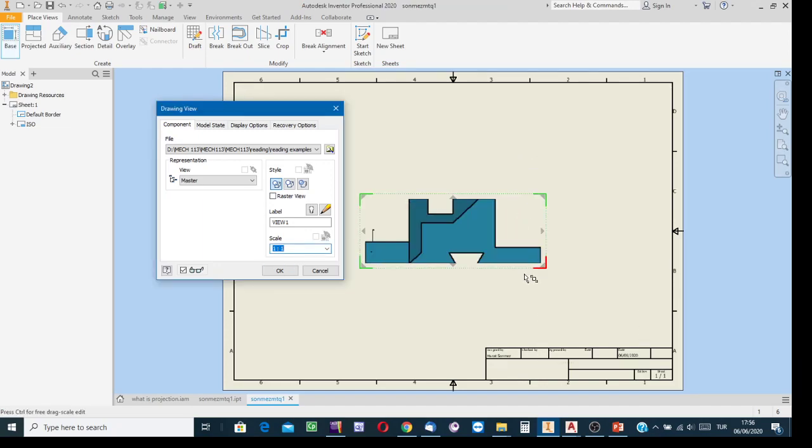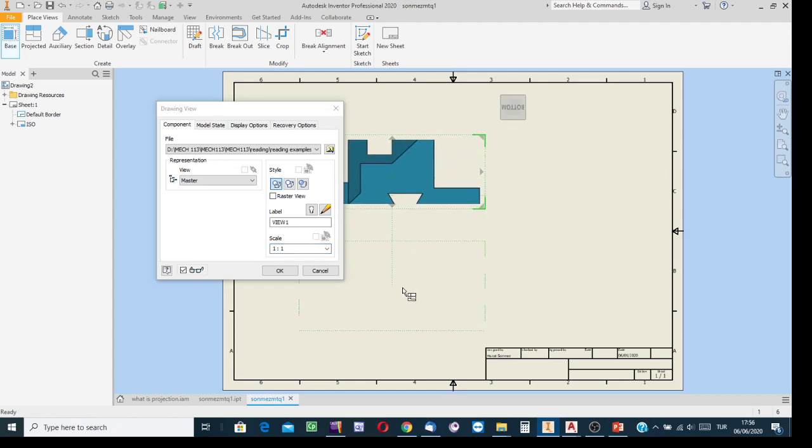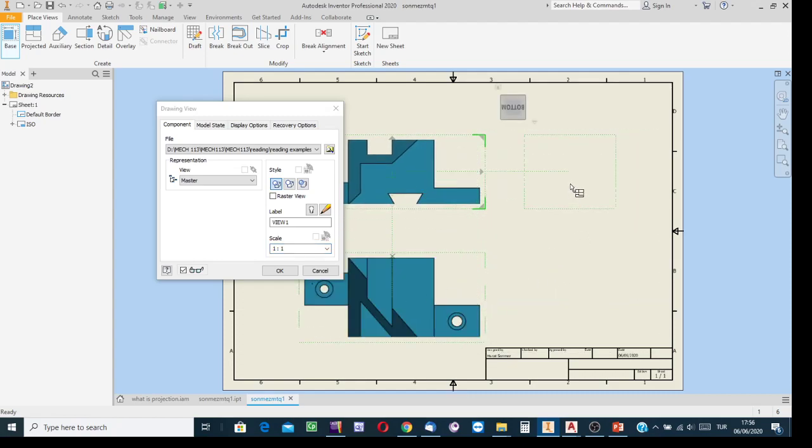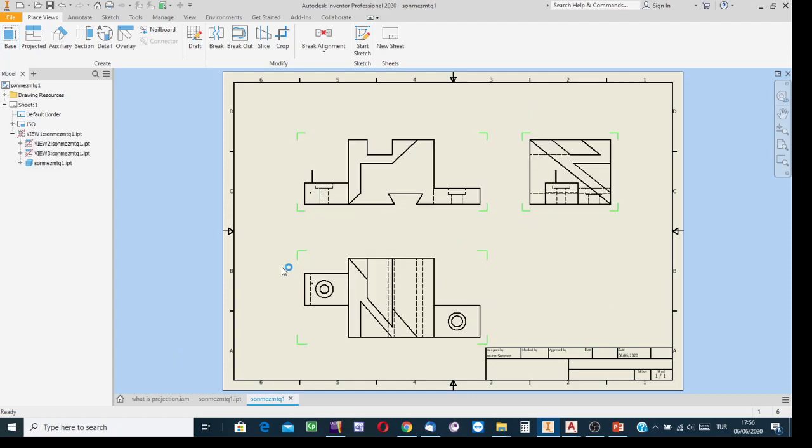Okay, front side view, click on this; left side, top side view, click at such a place on the paper, make a click at such a point, and then teach the software that over there you're going to create the left side view, and then say OK.